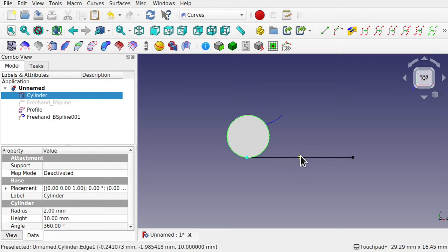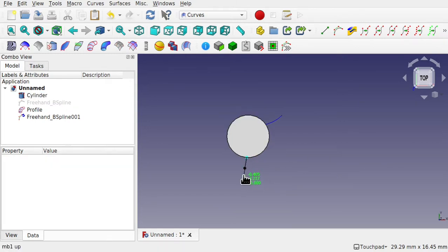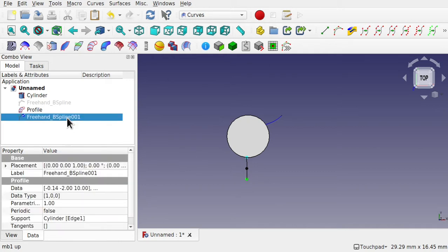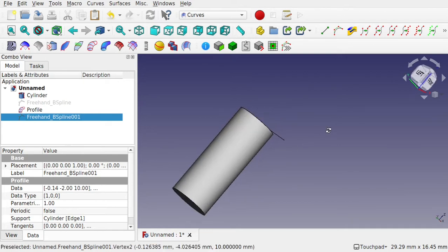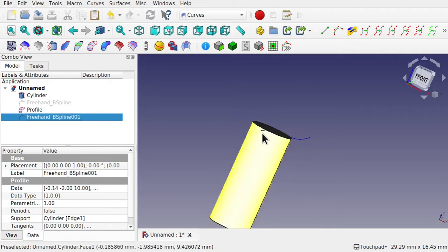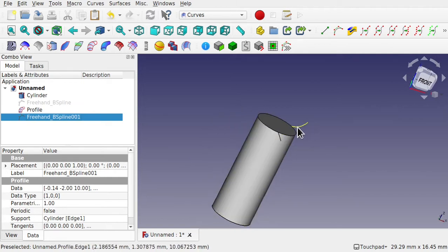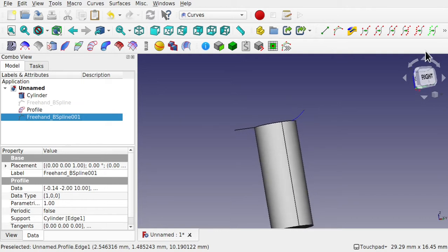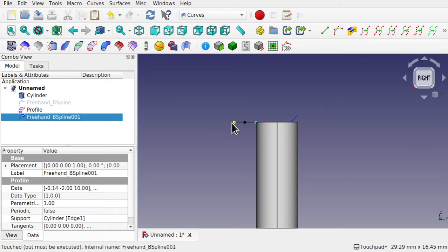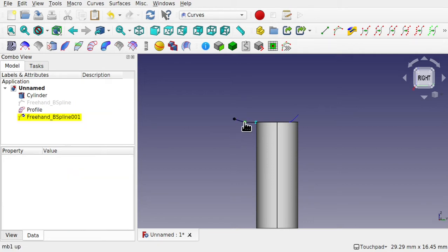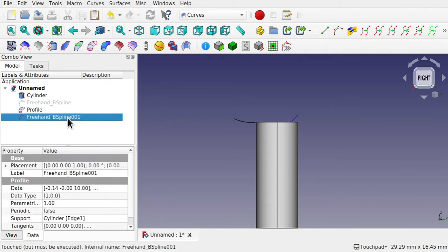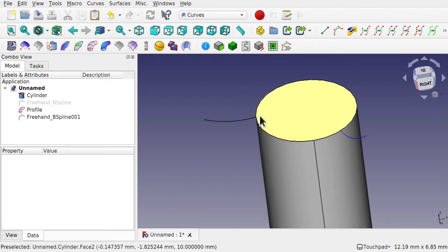Hit top, and we'll bring this around. I'm going to have this slightly bigger than this one. That'll do, double click it. That takes effect then. And I'm going to put some lip on this as well. I'm not going to mirror this one. I'm just going to do something different with this one, so it's not going to be as deep a curve as this one. So I'm going to come around to the right, double click it, and we're just going to give it a slight curve in here. Double click. Now we've got that in position.